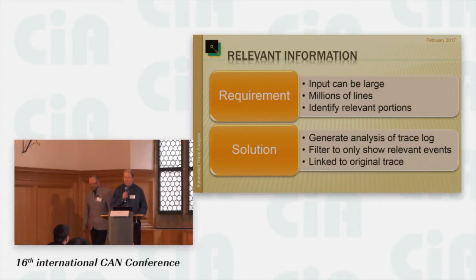So we can feed the CAN bus trace recording into a piece of software that can provide a degree of intelligence and is used to identify important and useful events. And we can use these events as an aid to narrow down the search. For example, a node boot-up can be identified as a potentially interesting event. A boot-up could be expected or perhaps unexpected and require further investigation. Node boot-up is a simple example, and a wide range of events could be identified this way, perhaps using analysis of CANopen protocols, such as LSS, to determine high-level operations when something may have gone wrong.